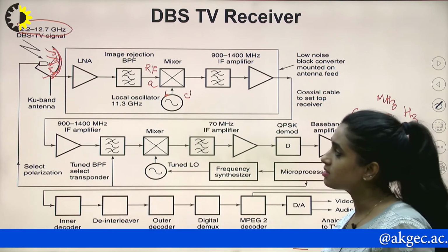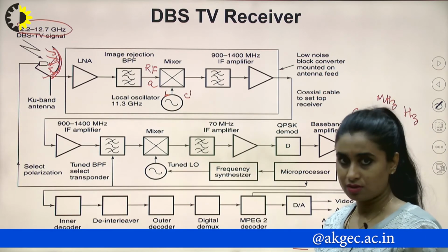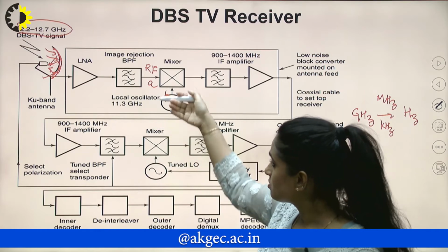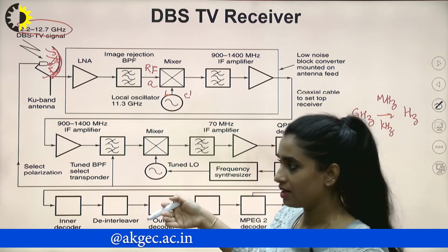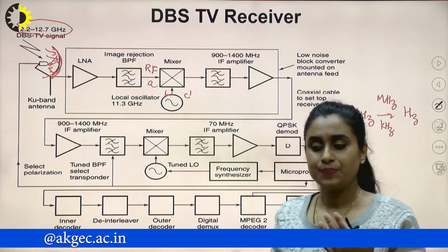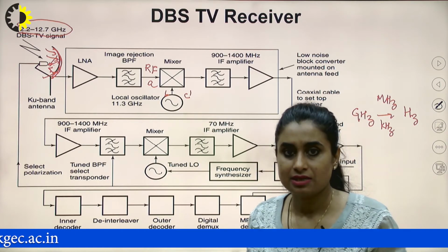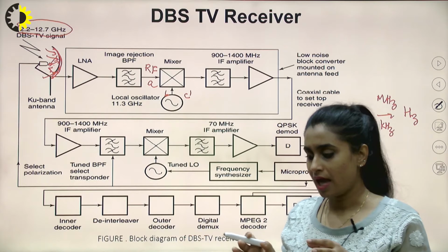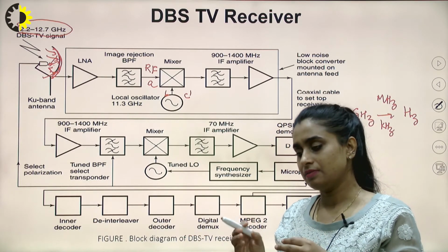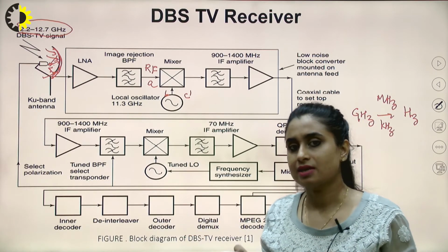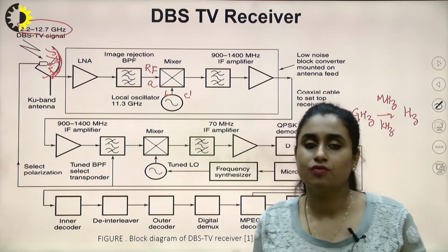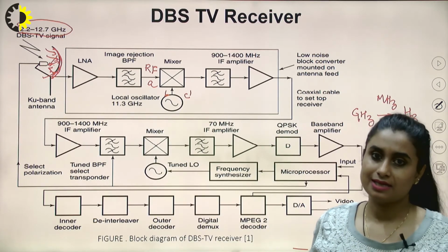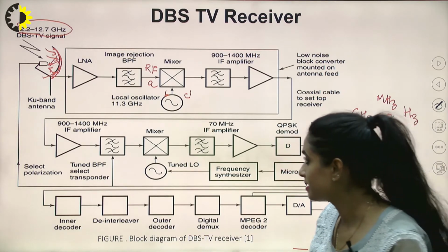So I'm using this in double conversion mode, a double arrangement of it. Using a double arrangement will help me acquire better, more accurate signals, reject more of the noise, reach the desired power level, and extract the exact signal we look for. So a double conversion arrangement is always better than a single conversion arrangement.